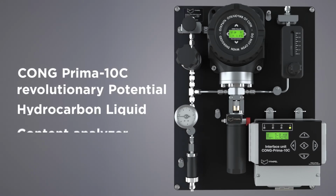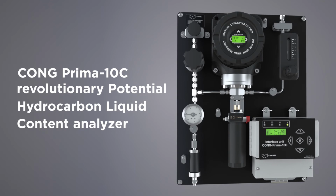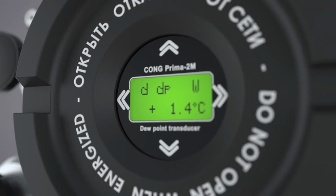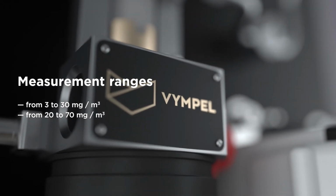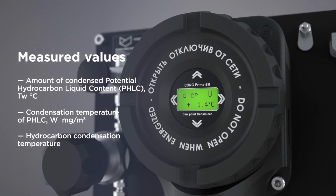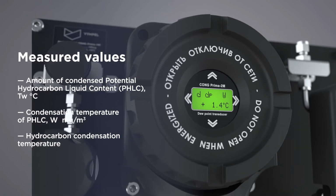The Prima 10C is the world's first online analyzer for measuring potential hydrocarbon liquid content in natural gas. The Prima 10C registers not only the hydrocarbon condensation temperature, but also other parameters as well. Given additional information about the temperature, pressure, and gas density, the analyzer calculates the amount of liquid that can be obtained from 1 cubic meter of natural gas.